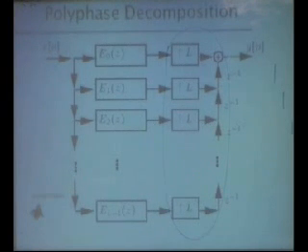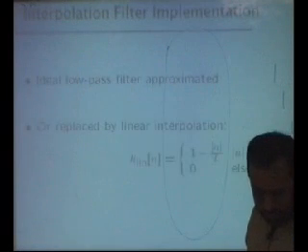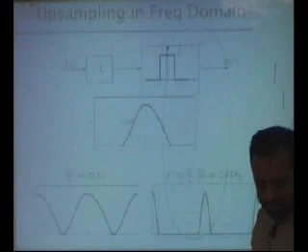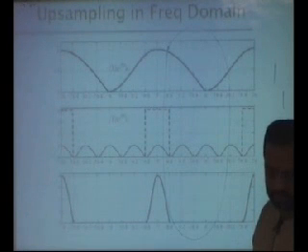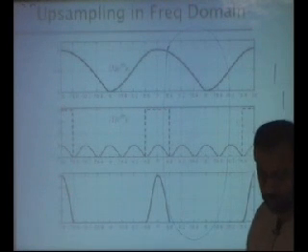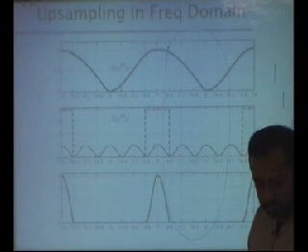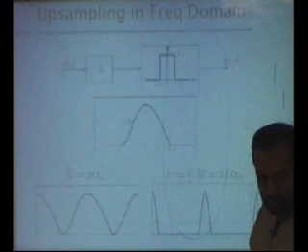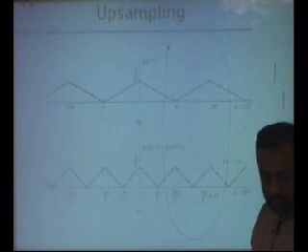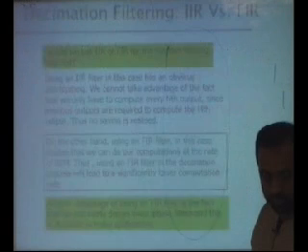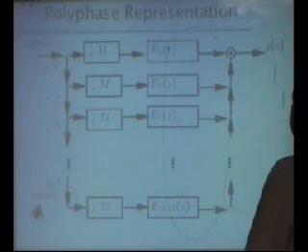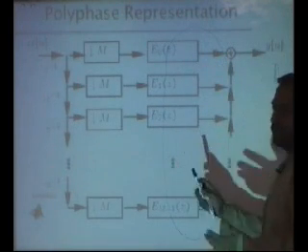To summarize, this is perhaps the last slide. Whenever you want to decimate or interpolate, and you do this a lot in all signal processing and image and video processing, it is better to decompose your filter into polyphase filters. It is always better to decompose a filter into polyphase filters, and that is very simple.